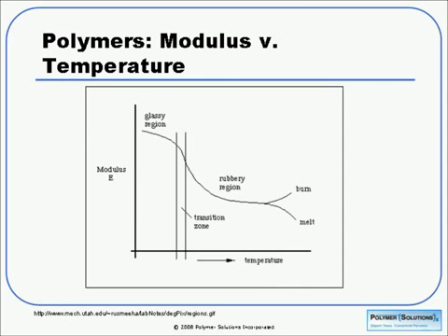So now we've kind of gone over Tg and Tm. What does this mean for our polymer systems? Well, this is a generic modulus temperature graph where we have modulus along the y-axis and temperature on the x. We see that as we begin heating our sample, we see a drop in the modulus, and that's going to correspond to our glass transition. Below that, we have a glassy polymer, and above that, we're in the rubbery region.